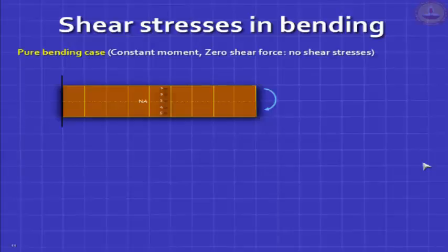So let's finish this. Let's look at what's happening. Let's take points along the depth of the beam, and the state of stress of these 5 positions is very simple. At the neutral axis there's nothing, and then you'll find there's compression further away from the neutral axis and tension further down the neutral axis, right? Linear variation.